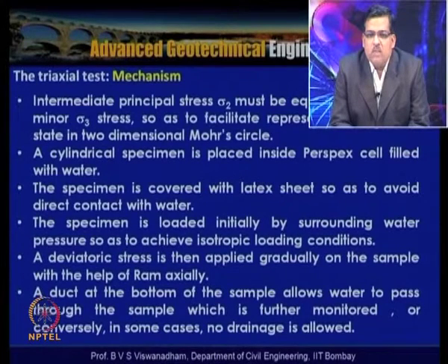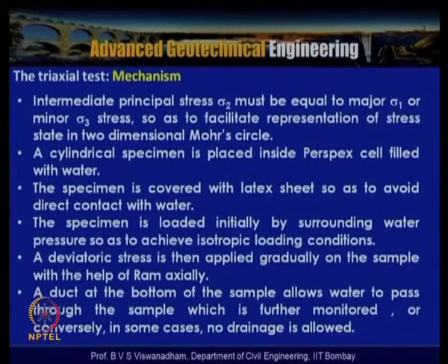A duct at the bottom of the sample allows water to pass through the sample, which is further monitored and can measure the volume changes, and the pore water pressure transducer measures positive or negative pore water pressures depending upon the stress history of the soil being tested.